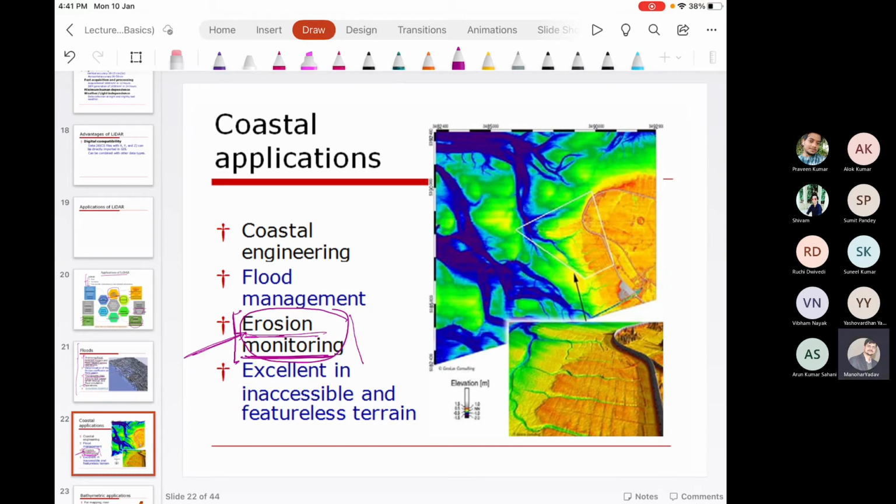Once the task is done, again excavation work is done, again do the laser scanning and generate a mathematical surface. When you differentiate two mathematical surfaces, which are 3D surfaces, because in LiDAR we have a Z, we have a depth of the point, you will get a total volume of material that has been excavated.